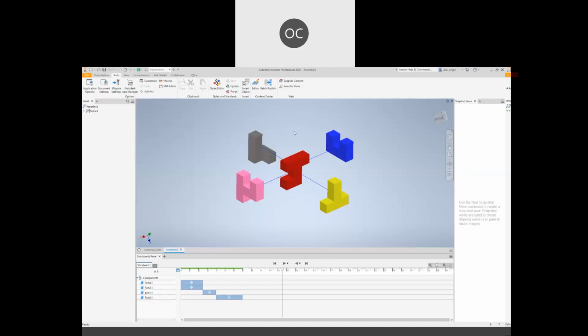The next thing that I would like to share with you is maybe you want to hide the blue trail. This one you call the trail here. Before we convert to a video, these will be the things that you would like to do to hide the trail. So you can go to your drawing canvas, right-hand click, okay, hide all trails. Hide all trails. So it won't be visible in such setting now.